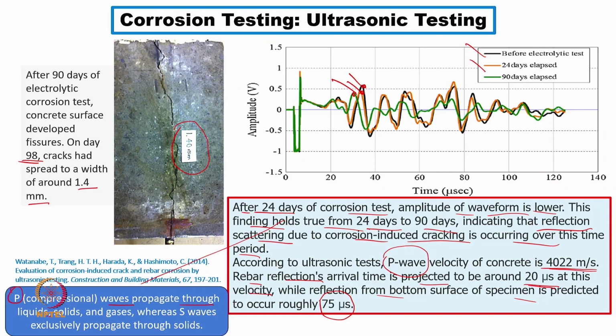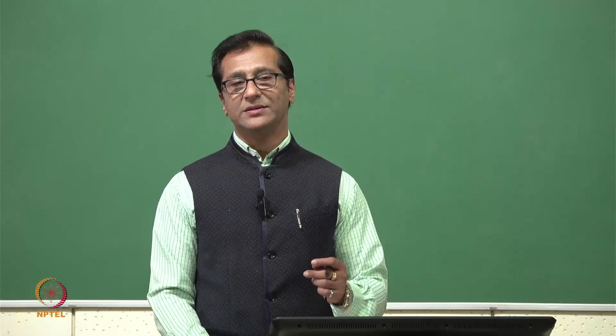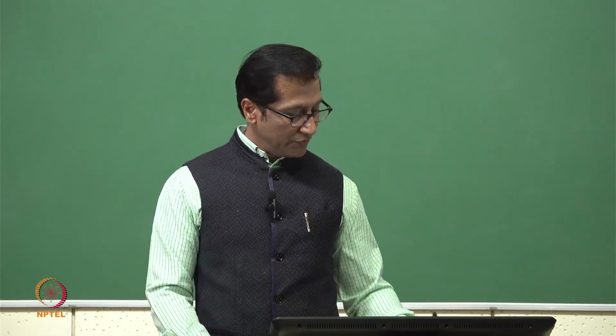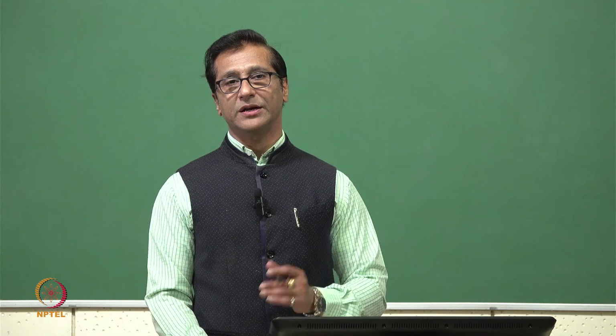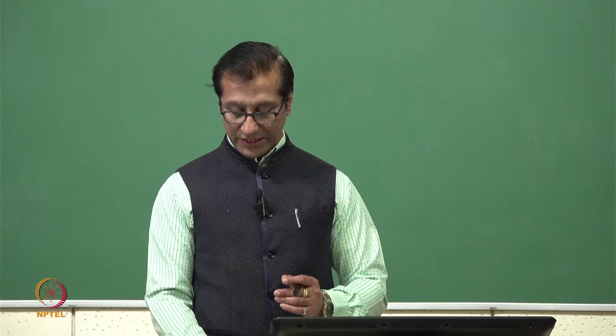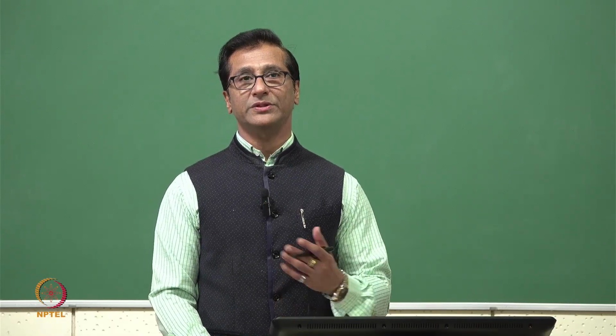Because it can be used in all the media. If there is a gas or crack, even this media, it can pass through that easily and gives a response. Why, if we use only the shear wave, then it will only propagate through the solid. It will not come back easily. Maybe if there are cracks in the situation, the P waves will be a better option and will give better results.